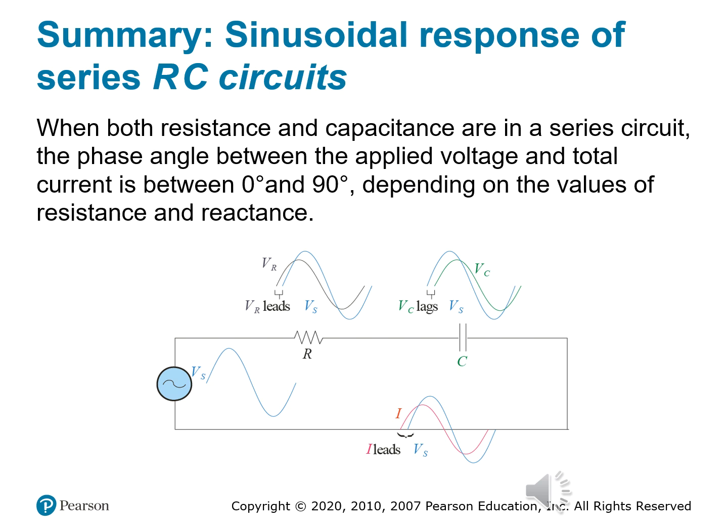So if you're looking at any of those preamps, these rely on timing distance between the voltage and the current. And let's go ahead and wrap up this slide with one final thought. The series RC circuit doesn't just pass voltage, it shapes it with a bit of phasor math. So you can predict what shaping happens down to the degree. And next, we're going to explore how these phase shifts map onto impedance and, yes, admittance.